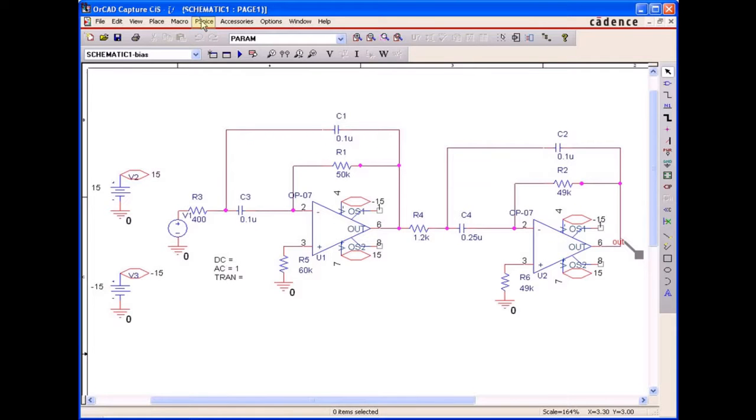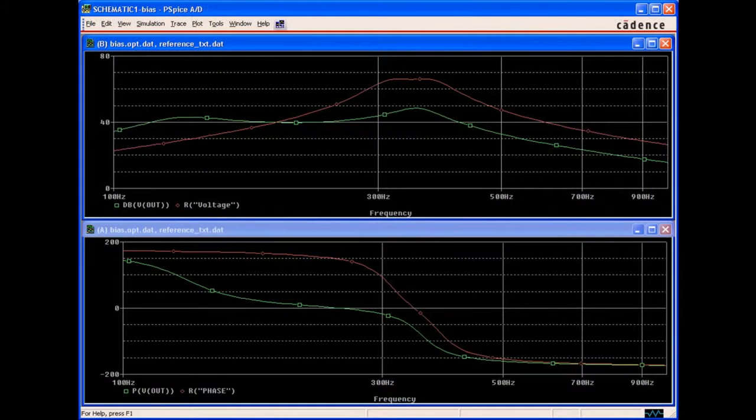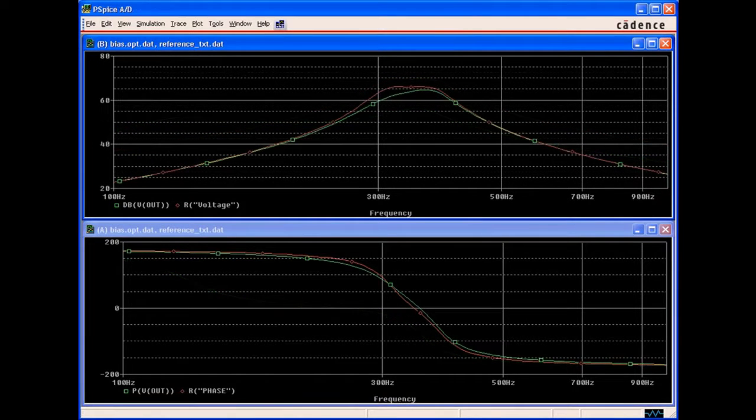The goal of curve fitting using PSpice Advanced Analysis is to optimize a circuit output against a target specification represented by a waveform. Normally, the optimizer capability in Advanced Analysis is used to optimize against defined measurements and values. But in this example, we're going to use the curve fitting capability of the optimizer to match the output curve of the design to a reference curve.